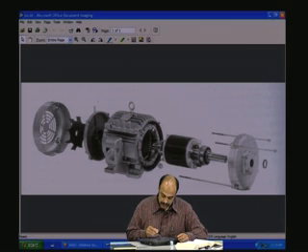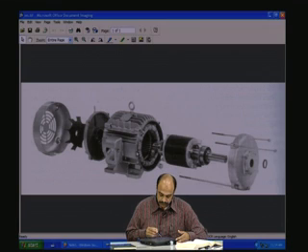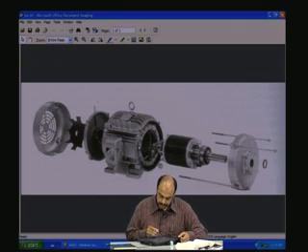This whole coil is wound on the stationary system, this yoke, and that is the stator, which is anchored onto the ground through these foot plates, and that doesn't move. So once the poles are fixed in space, they don't rotate. What makes the flux rotate is by virtue of the three-phase source that you supply, which are 120 degrees apart.